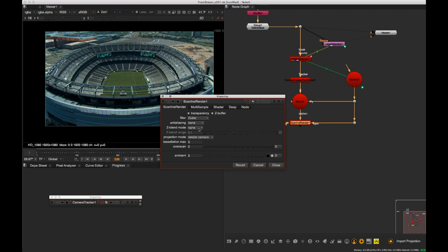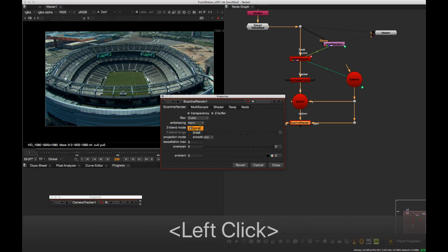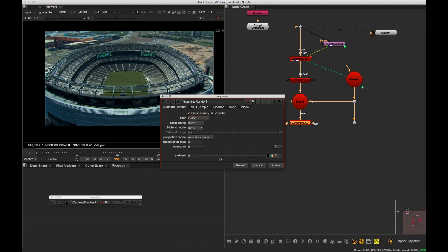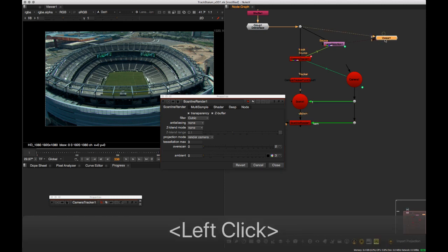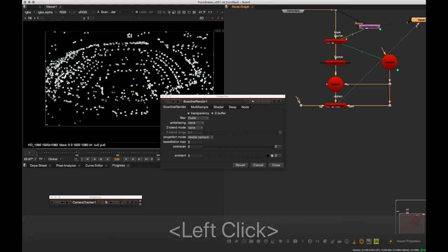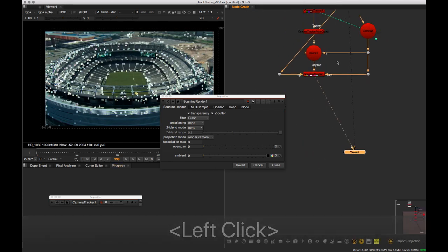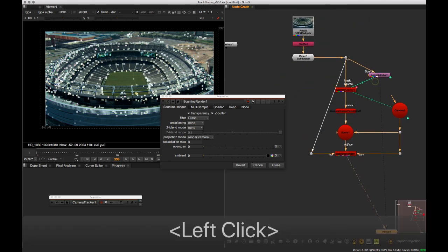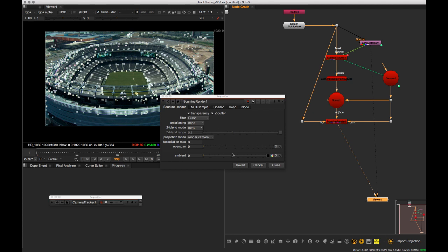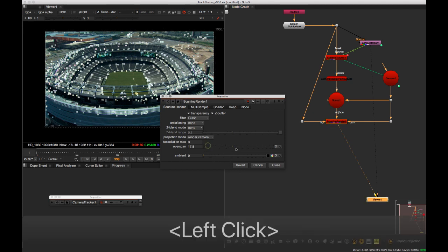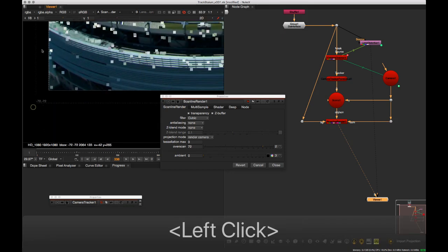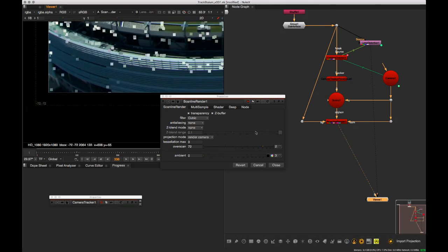There's a variety of settings, including the Z-blend mode, which blends things in depth, the anti-aliasing, the filter that's applied to resize things. There's overscan, which if we look through the scanline render, and let's just reattach it. Oh, and of course there's this point cloud, which is being rendered as points. If we reattach it to the actual plate here, we can overscan it by 72 pixels. So there's an additional 72 pixels of overscan.